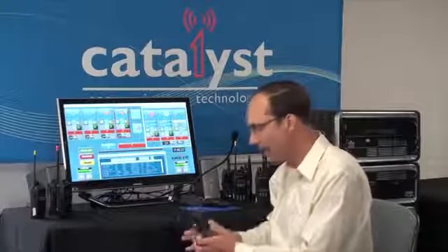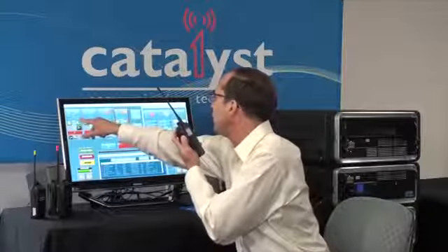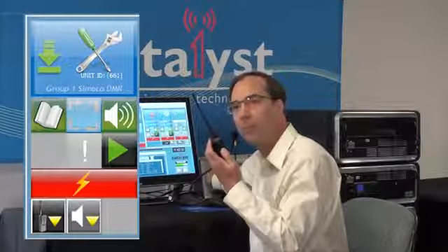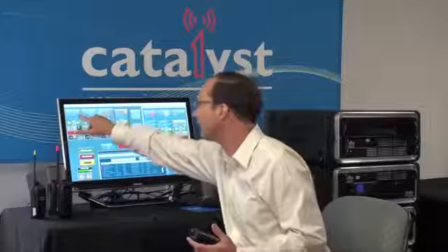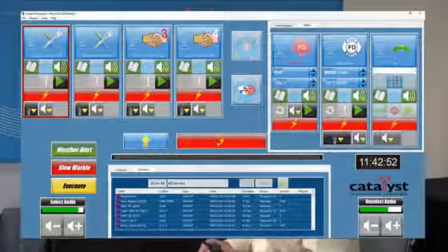We'll begin by taking a SIMOCO 660 portable radio, which is tuned to DMR talk group 1, and keying that radio up. When I do so, you'll see the unique unit ID for that radio, and when I turn the audio up on the speakers, you'll hear the audio coming through my console speakers. The dispatcher can select that module either using the touch screen or the mouse and can transmit back to all of the subscribers who are listening to that particular channel.